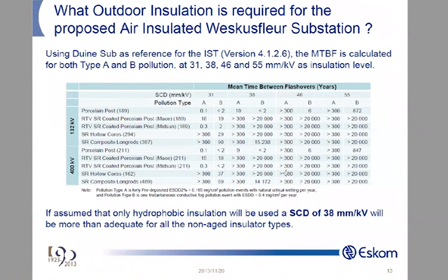Low molecular weight silicones. Low molecular weight means there's very few molecules there, so it's a small little chain. It's a low molecular weight chain, and this little chain is this little thing that is now migrating out. And this polar thing here is attracting it, and these oxygens here are attracting to the polar. Out migrates. These low molecular weight silicones migrate to the surface, and they start encapsulating the pollution particle, all around.